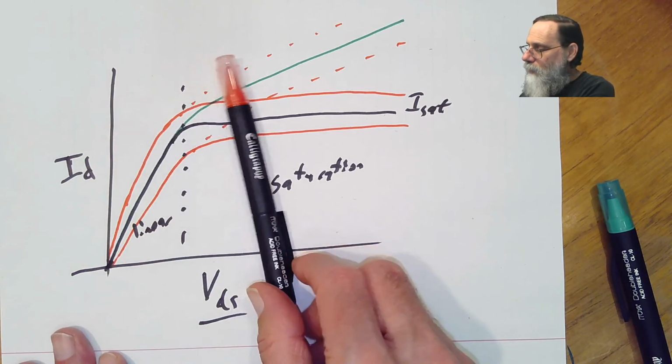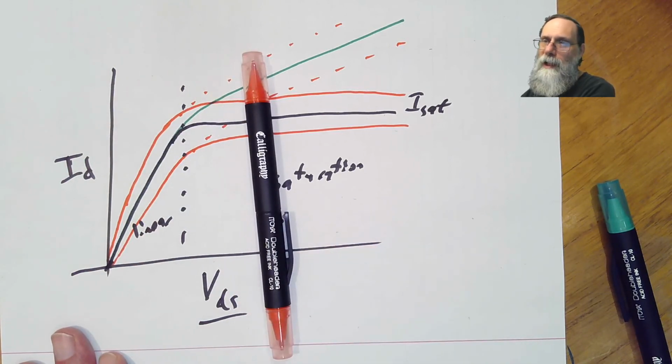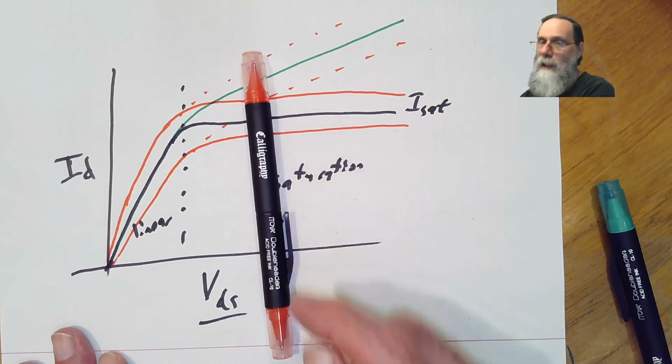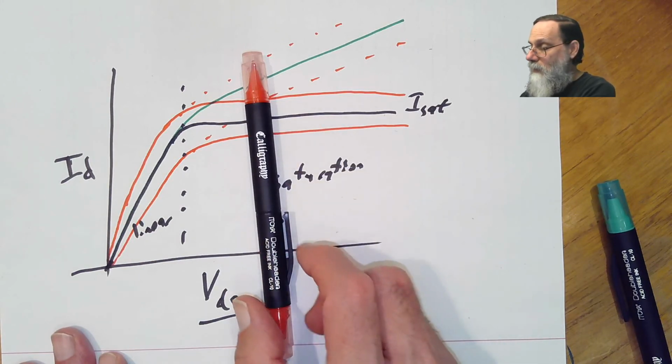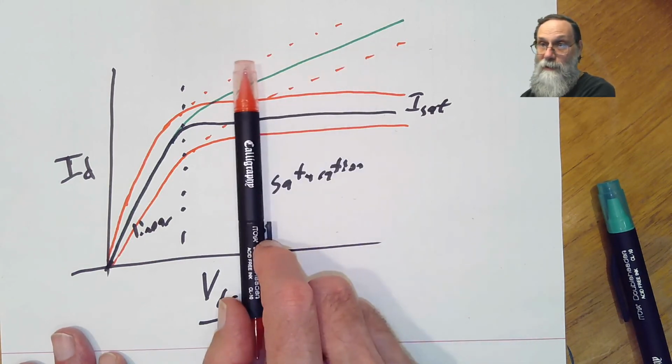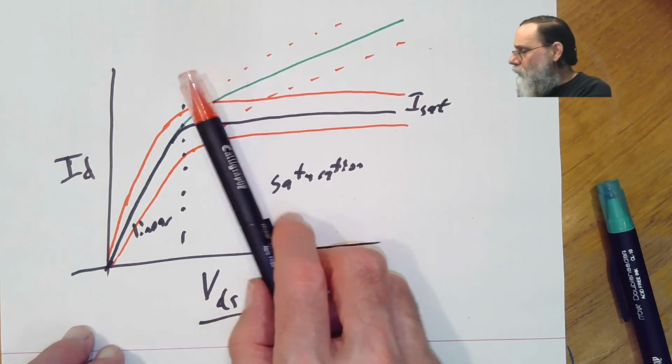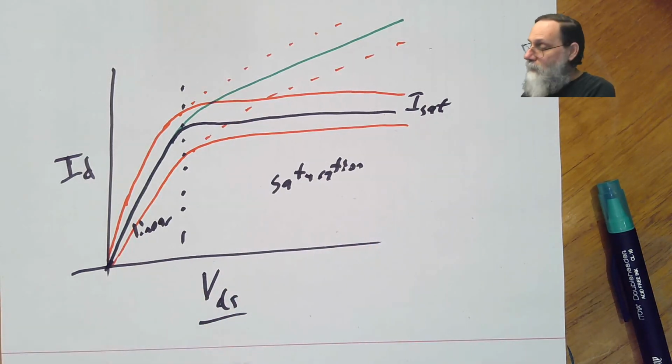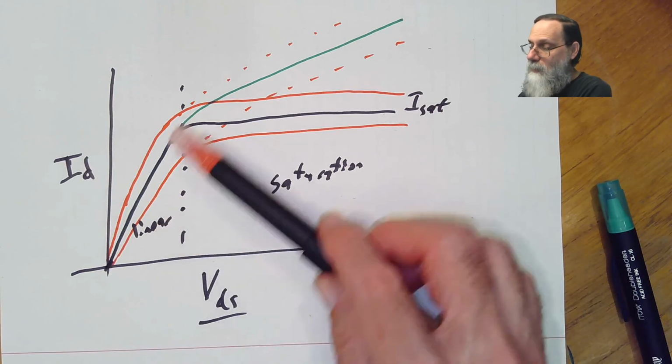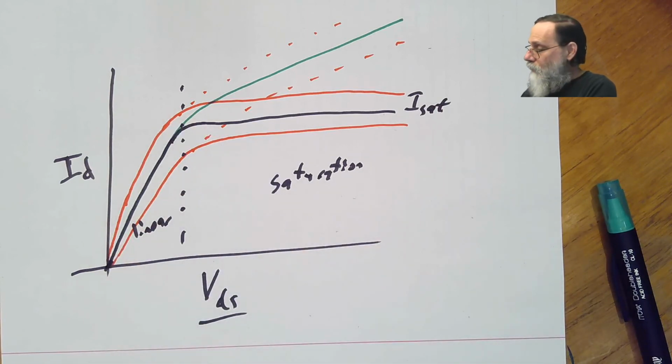So usually the electret microphones are designed so that the field effect transistor is somewhere in the saturation region. We can also take a look at the standard models that say what the saturation current should be, what the current in the linear region should be, and most importantly, what that says about the transconductance, essentially the gain of this transistor.